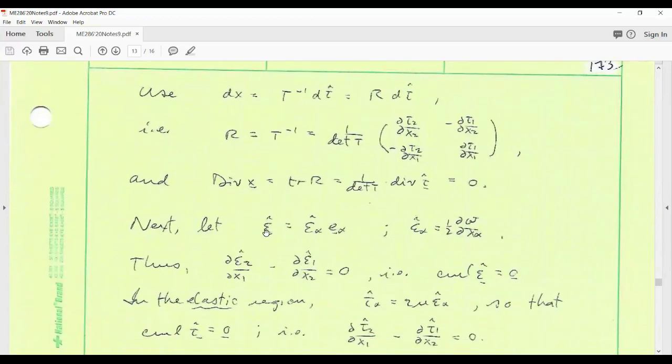We can write the total strain vector in terms of Cartesian components. They'll be given this way, because epsilon hat is the gradient of W, so the Cartesian representation is this in X space. Because epsilon hat is itself a gradient, of course it has 0 curl. In other words, this equation is satisfied. The two-dimensional curl is 0. D epsilon 2 hat dx1 minus d epsilon 1 hat dx2 is identically 0. That's just from the equality of the cross partial derivatives, the second derivatives of W.